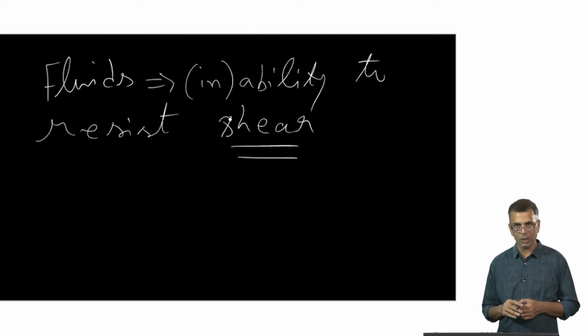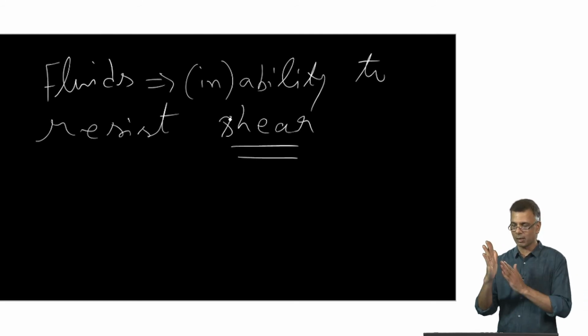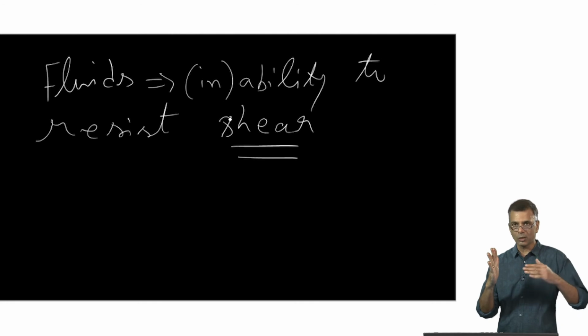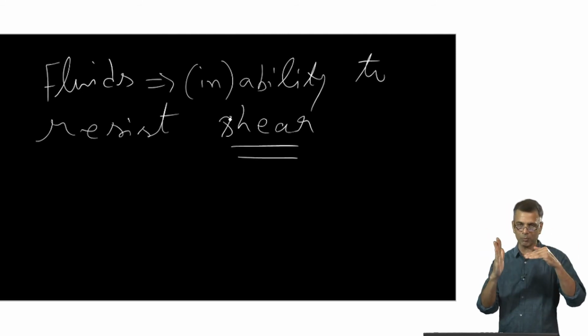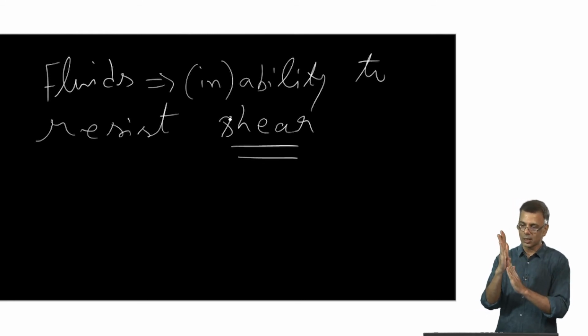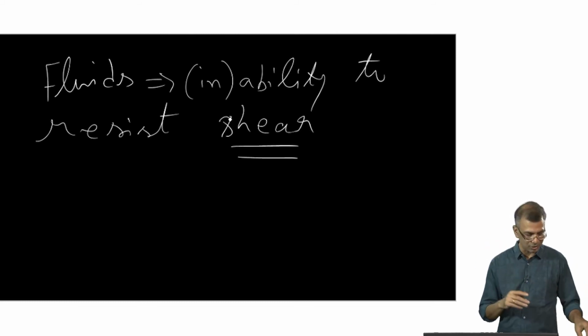Essentially, you think of a surface, and there are two kinds of stresses, two kinds of force per unit area, you can think of. One is a normal, so there's the area element, and the normal is like so. So one is a normal force like this, and you are applying a normal force, and the force per unit area would be simply the result of this normal force. The other kind of force you can think about is when the force is tangential to the area, to the surface element, like so or like so, and these are called shear stresses. This is called a normal stress, and this or that is called a shear stress.